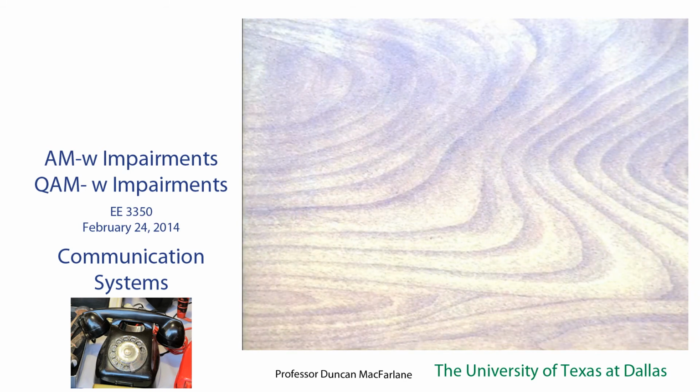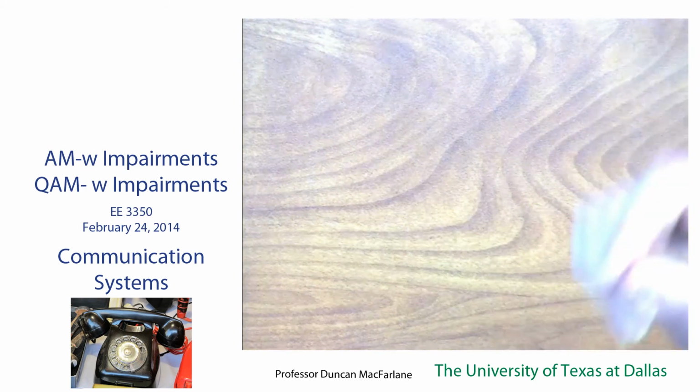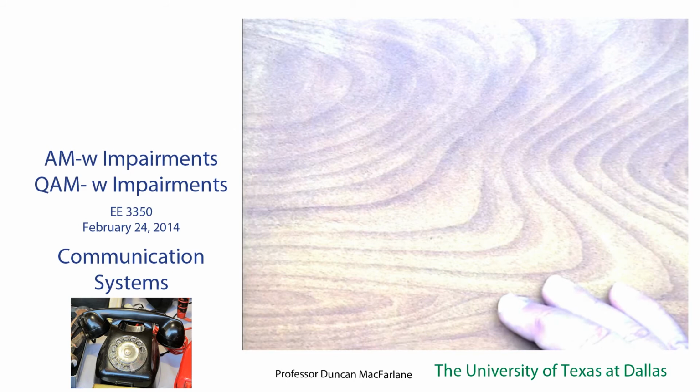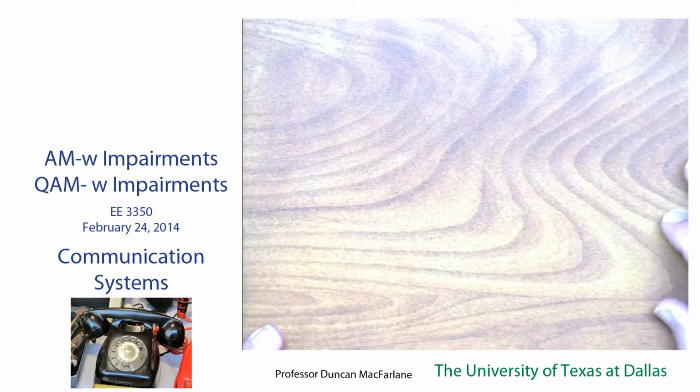Right? So think about it. You're doing a design. It depends on that resistance value. You're shipping 100 boards, 5% resistances. Not everything is going to be at 100 ohms. Some are going to be put down to 95, 98. Some are going to be at 102, and some are going to be at 105. And all the boards have to work. Oh, but guess what? On a board, there's going to be maybe 100 resistors, and maybe 50 capacitors, and different transistors.